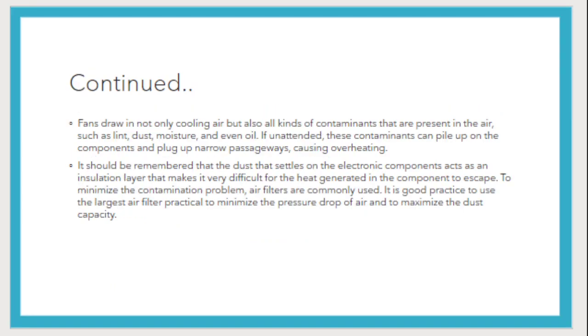Fans draw in not only cooling air but also all kinds of contaminants that are present in the air, such as lint, dust, moisture, and even oil. If unattended, these contaminants can pile up on the components and plug up narrow passageways, causing overheating. It should be remembered that the dust that settles on the electronic components acts as an insulation layer that makes it very difficult for the heat generated in the component to escape.